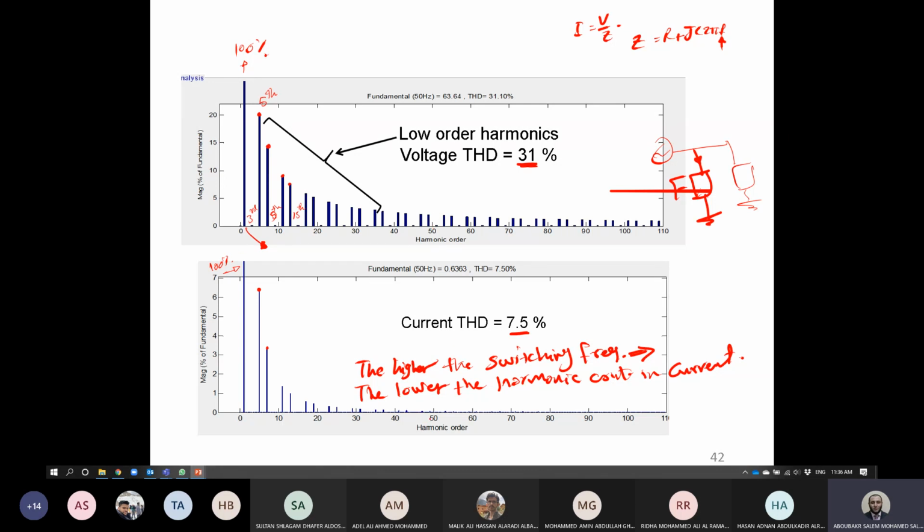And at order 50, as you can see here, you already have a few components, maybe 2 or 3 like that, but it's not appearing here because the impedance is very high. So we expect that if we could shift this value 20 to a frequency order of 50, it will be much more attenuated here, and in this case, you will remove all of these harmonics. Actually, this is the idea of pulse width modulation.